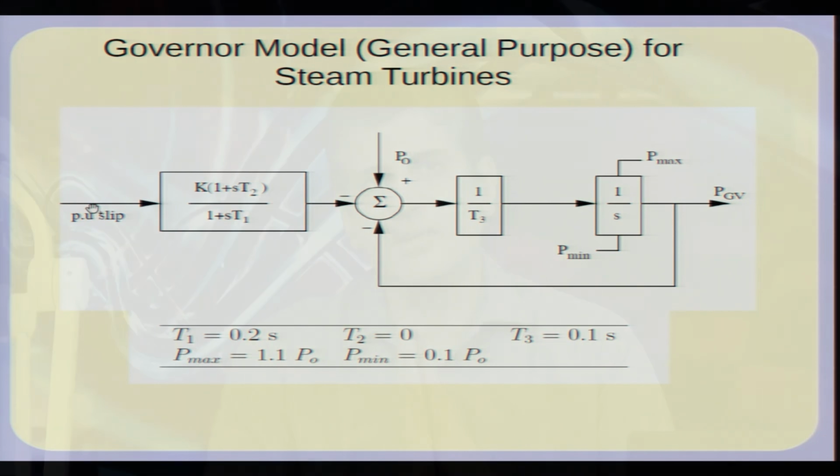Now, you may ask a question: why talk in terms of proportional controllers when you can have an integral controller? Well, if you have got a single generator connected to a load, you will find that in fact, you can use an isochronous governor which regulates the frequency quite well.